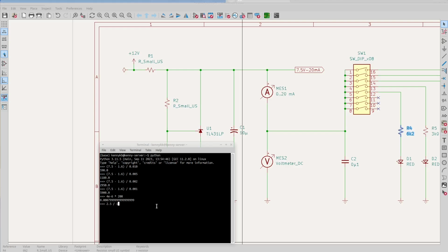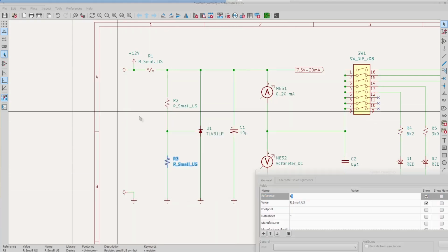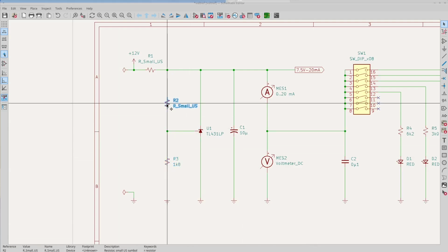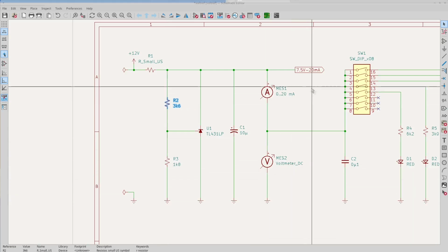We need at least 800 microamps in the divider, and the lower divider resistor will drop 2.5 volts. So it needs to be at most 3.1K. I'll go with a standard value about half that, 1.8K. I can live with 1.4 milliamps through the divider. The top resistor will drop 5 volts, so 3.6K is right for that.